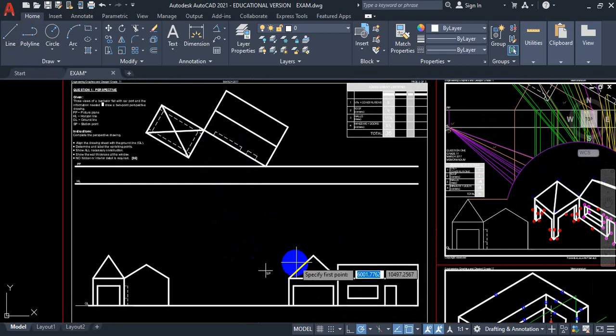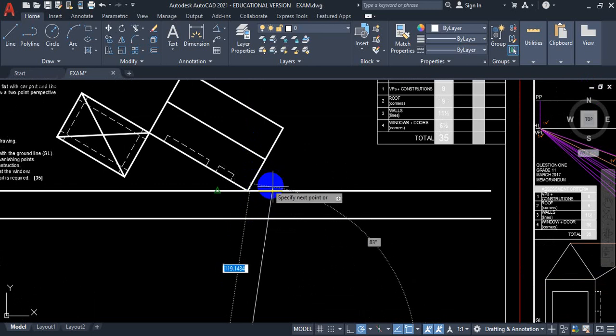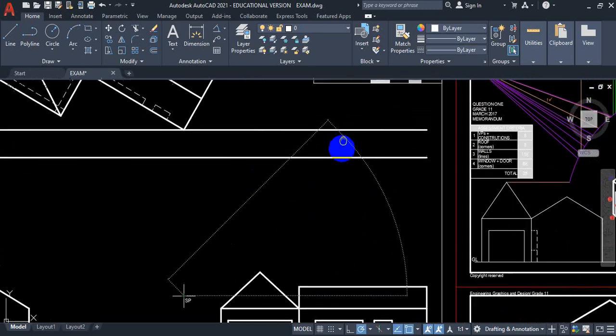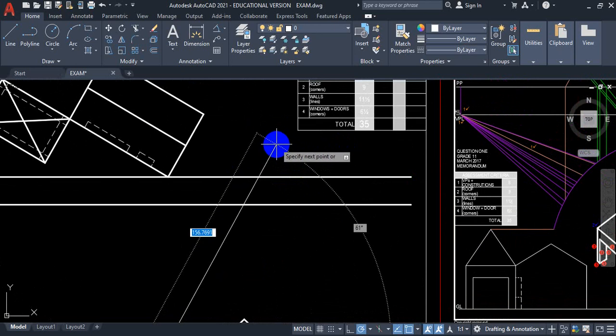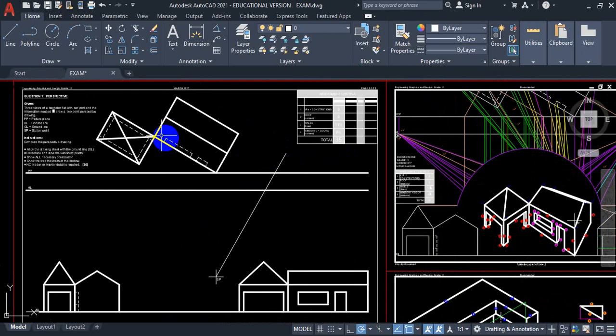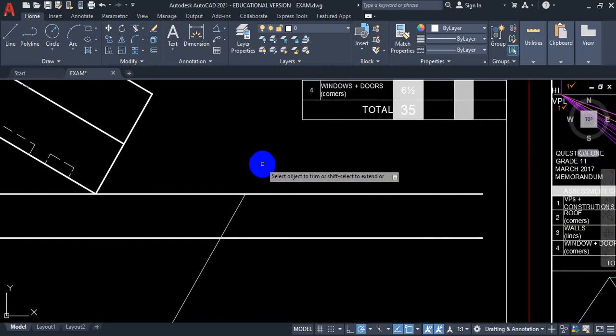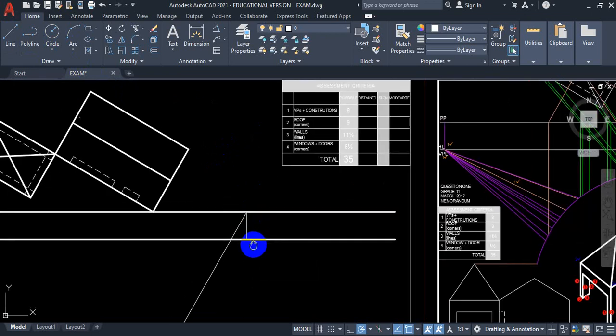So we're going to start by drawing from station point. And remember, the angle on this side is 60 degrees. So if you go to draw a 60-degree line, that will go to picture plane. Once the line hits the picture plane, all we need to do now is to drop the line to horizon line from picture plane. So this is now our RVP.